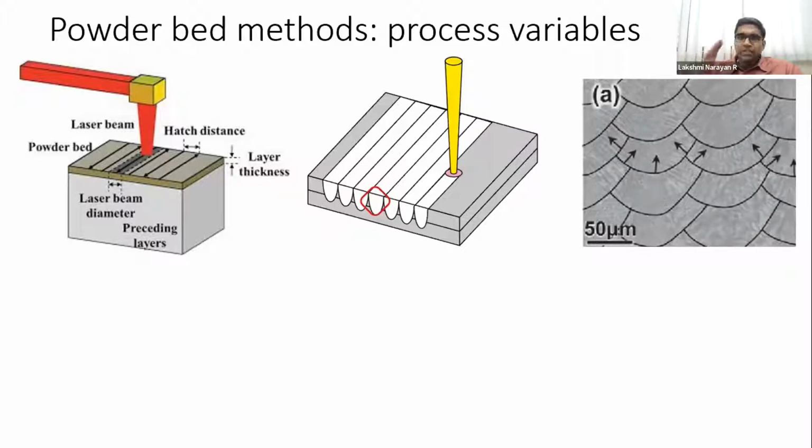So you would see a lot of these very nice dendritic and columnar structures in 3D printed materials when you look at the microstructure. But if you just consider the melt pools, these constitute the mesostructure of the material. Okay, this is at scales higher than the grain size of the material, and hence is referred to as mesostructure.